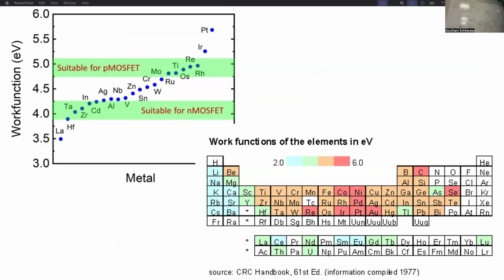So here you're showing the work function of metals, but we do all the depositions, all the nitrides. Why do we do that? Because that actually changes the work function slightly. Usually when you deposit these things and you anneal it, a lot of metallurgical things happen. They alloy and all that stuff. That gets very complicated. For your case, you can just use a metal, that's fine.